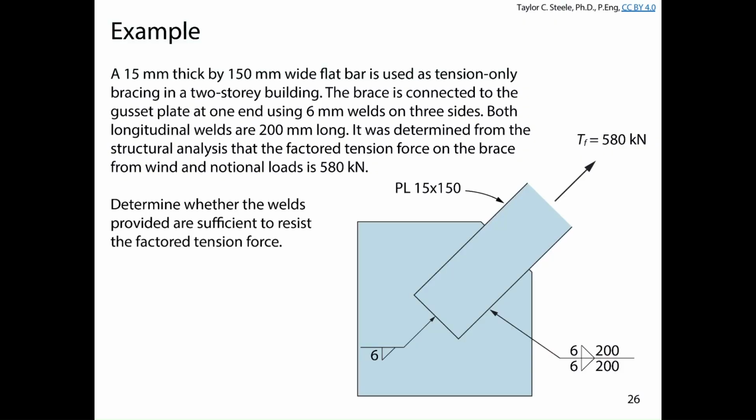What do the weld symbols mean? That's an important thing. Yeah, exactly. So let's deal with this one first. 6 millimeter weld, this side of the arrow, right? So we're going to have a 6 millimeter fillet weld. There's no length given there. That implies weld the full width.